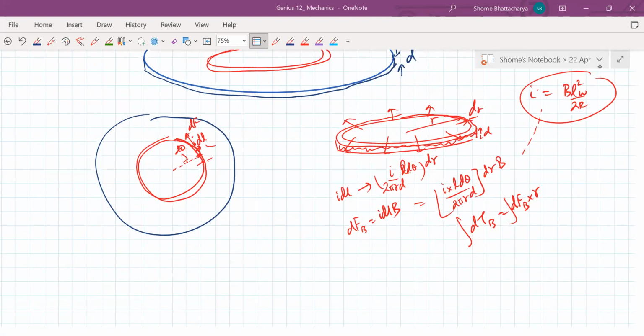No? You will have to take the rings, having a thickness, I mean, you'll have to take an element on the ring having this thickness equal to r d theta and this thickness equal to dr. And first calculate the torque because of the force that is acting on this element. That is the df which I've written. But that df is proportional to dr into d theta. Then you integrate across theta. So you'll get something into dr. That is the torque acting just because of the ring.